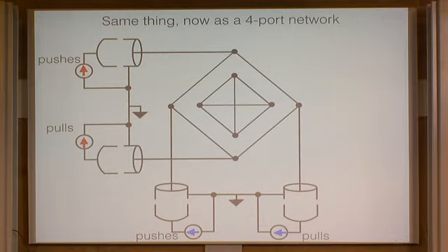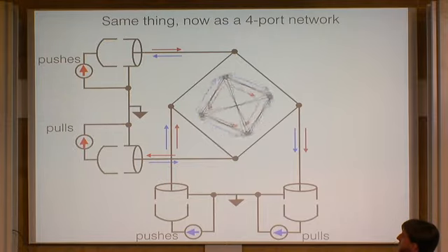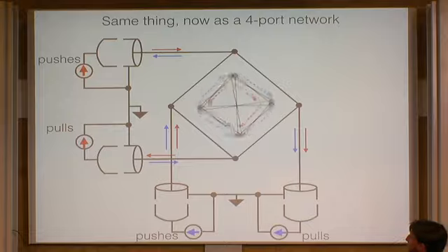So let's break it up. You can imagine having now sort of a balanced drive of this circuit, where I now have two ports on either side here that can have the same reference. And if we have two sources on the input here that push and pull down there, you get exactly the same situation that I had in the last slide. And it'll do exactly the same thing. You can make this thing look like a gyrator.